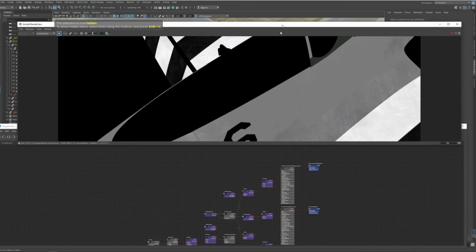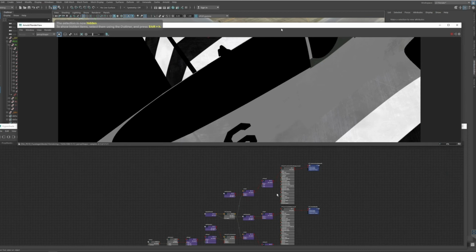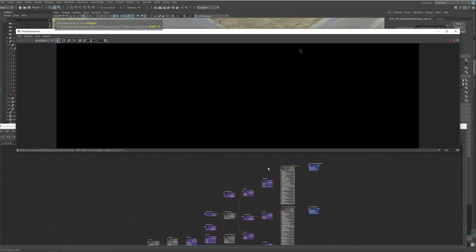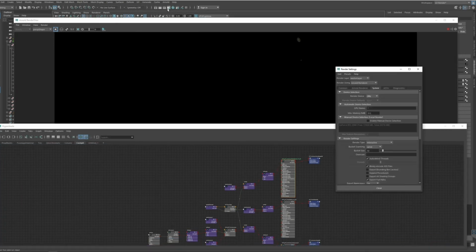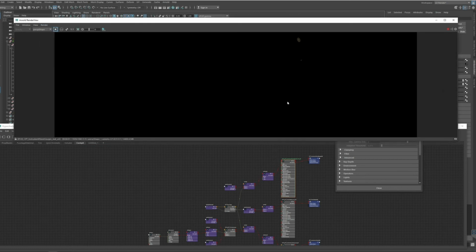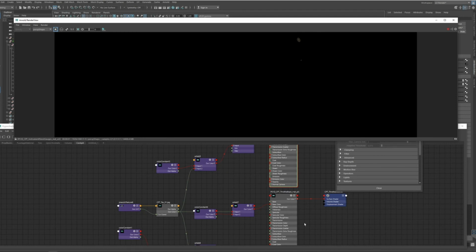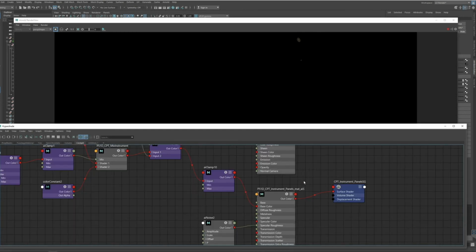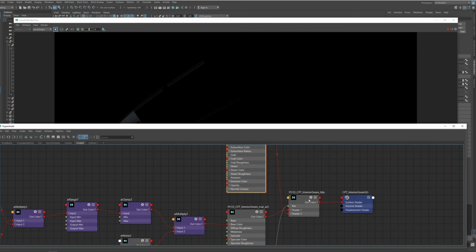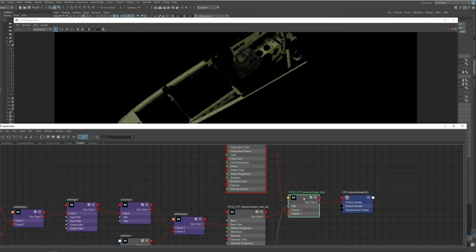So I still have this fuselage material selected, but as soon as I, for example, select this material, so Arnold is slower on the CPU. Let me just do one thing here for preview purposes. Let us just disable adaptive sampling. Let us go down to 2 samples. Progressive refinement is on. And let's search for a material that is actually easier to see right there. Let's go to interior dark metal. Let's go to cockpit interior green.